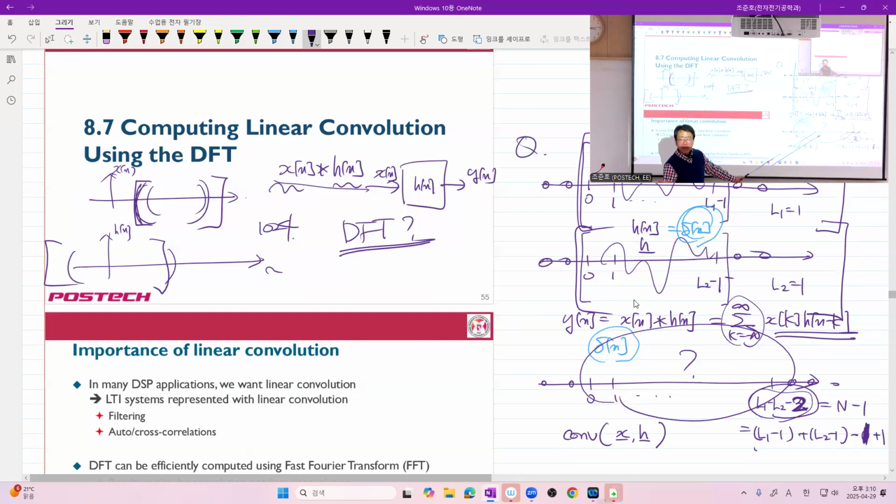And what you do is that you perform inverse DFT, and after some possible scaling, you put that vector here. Got it? That is the idea. And if n is chosen, for example, as 2 to some integer power, then fast algorithms such as FFT outperform ordinary convolution in complexity.